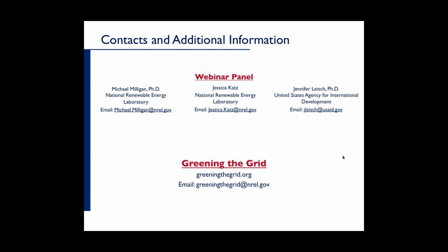Okay, I'll repeat the question because I'm not sure if anybody heard me. The question was explain more about why we do not need any storage when we have 30% energy from wind and solar. The answer to that question is because we typically have generation on the system that can be controlled or even turned off. And so during periods of high wind or high solar, we can turn down a gas unit, or we can turn down a coal unit, as you saw in some of the graphs. And that sort of makes room, if you will, for the wind or the solar energy.